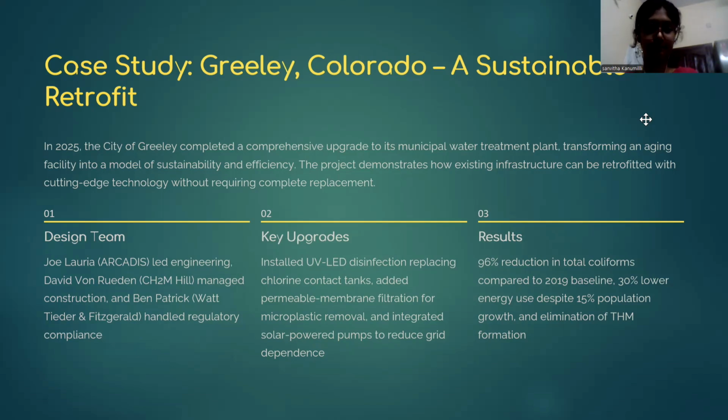So the design team was Arcadis-led engineering, David Von Reden managed construction, and Ben Patrick Tidrear handled regulatory compliance. And key upgrades are that they installed UV LED disinfection, replacing chlorine contact tanks, added a pre-membrane filtration for microplastic removal, and integrated solar-powered pumps to reduce grid dependence.